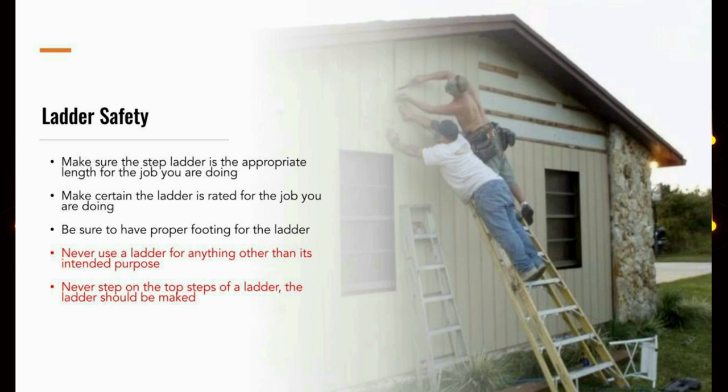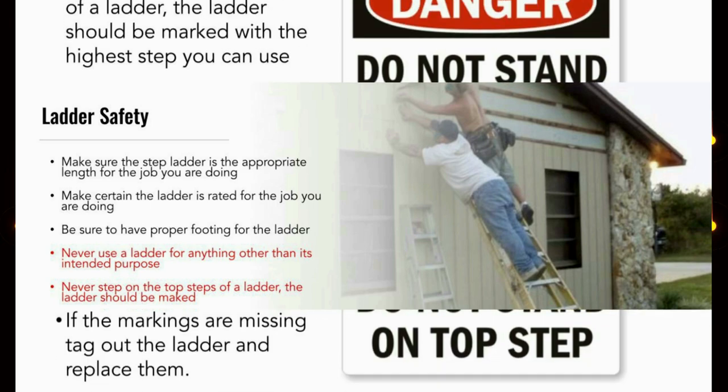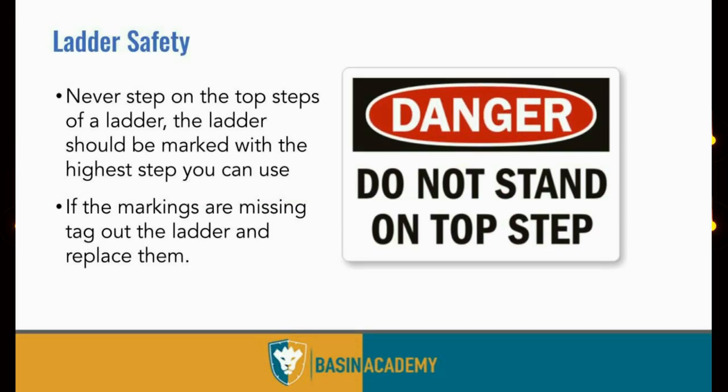Never use a ladder for anything other than its intended purpose. Never step on the top steps of a ladder. As I said earlier, the ladder should be marked. To repeat this, ladder safety, never step on the top steps of a ladder. The ladder should be marked with the highest step that you can use. If the markings are missing, tag out the ladder and replace them.